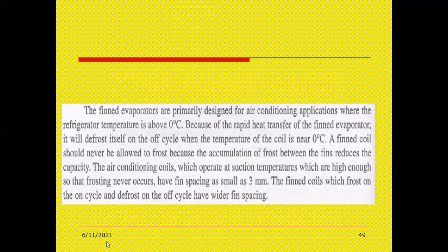That's why frost is never allowed, because accumulation on the fins reduces the capacity. The air conditioning coils will operate at suction temperatures which are high enough so that frosting never occurs, having fin spacing as small as 3 mm. The finned coils which frost on the on cycle and defrost on the off cycle have wider fin spacing.